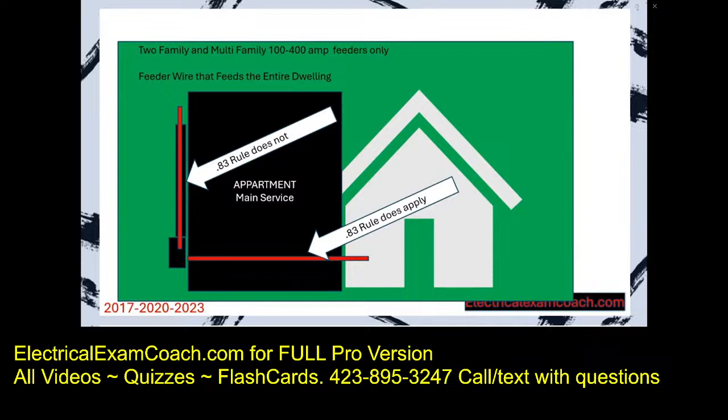Whether you're doing single family dwellings only or you're doing the individual units of the apartments, you're going to be able to use a smaller wire based off that table than you would if you went and sized it like normal. And over a year's time, that could save you a lot of money. So that is when the 83% rule does and does not apply.